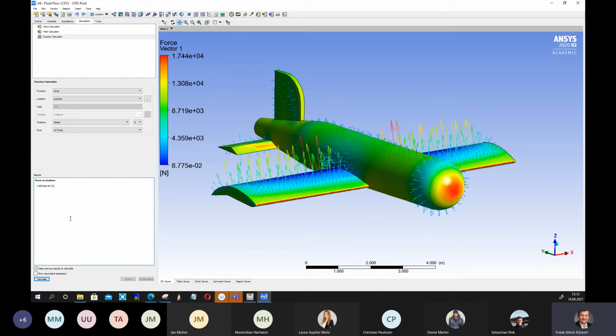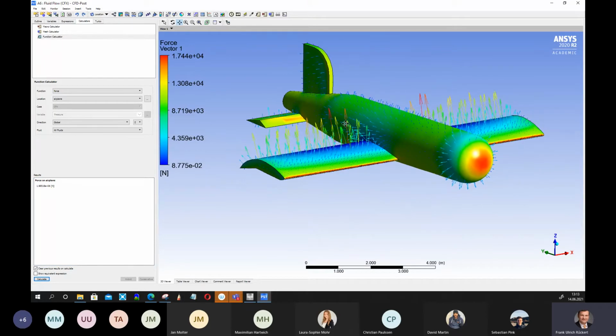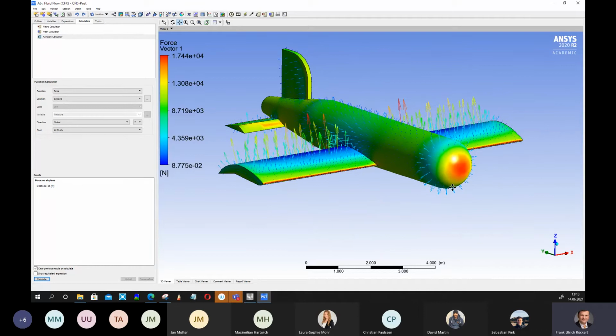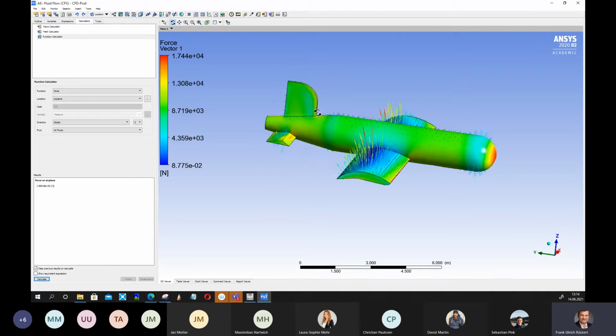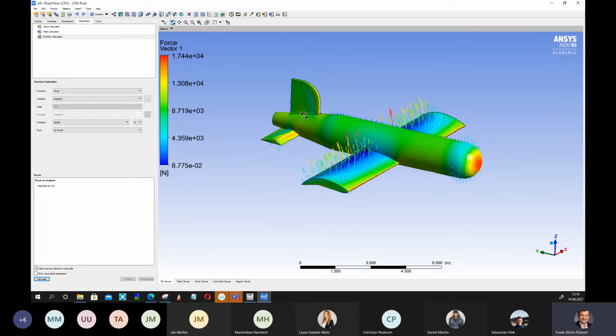And that's really cool. It's a high number. The airplane will fly. Make sure you take here global set direction, and that you make your construction so that the lift is in set direction. And make sure it's a positive value, because positive value means you have a lift upwards. If you get negative numbers with a minus, the airplane will go downwards, and then your design of the wing is not really good.